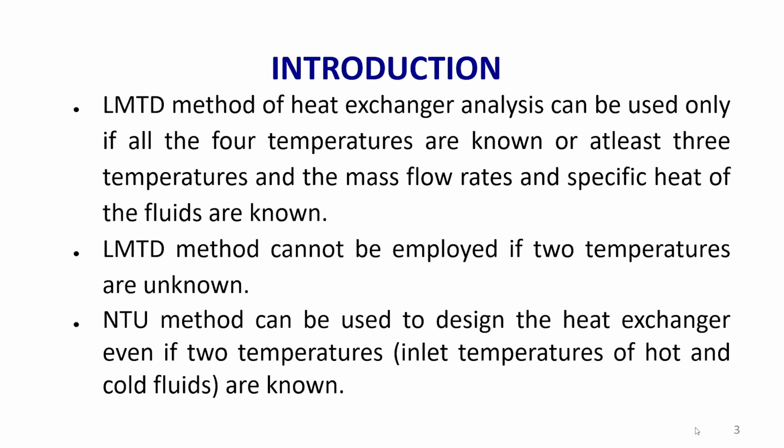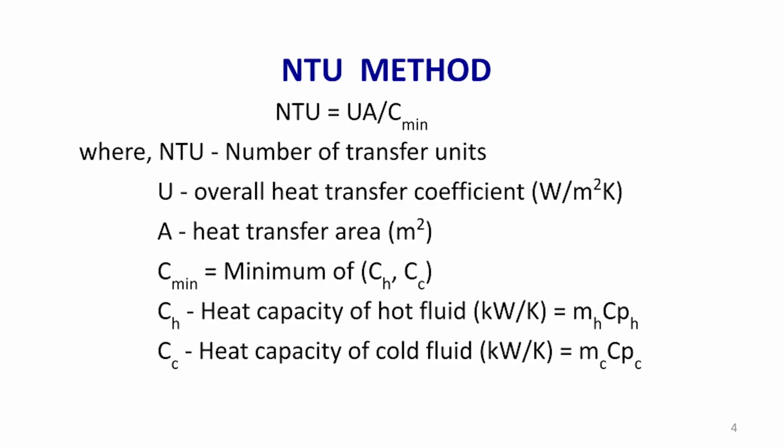The NTU method can be used to design the heat exchanger even if two temperatures are unknown. Normally those two temperatures given will be capital T1, the hot fluid inlet temperature, and small t1, the cold fluid inlet temperature. In the case of the LMTD method, we use the relation Q equals UA LMTD, where the LMTD formulas are different for parallel flow and counter flow.